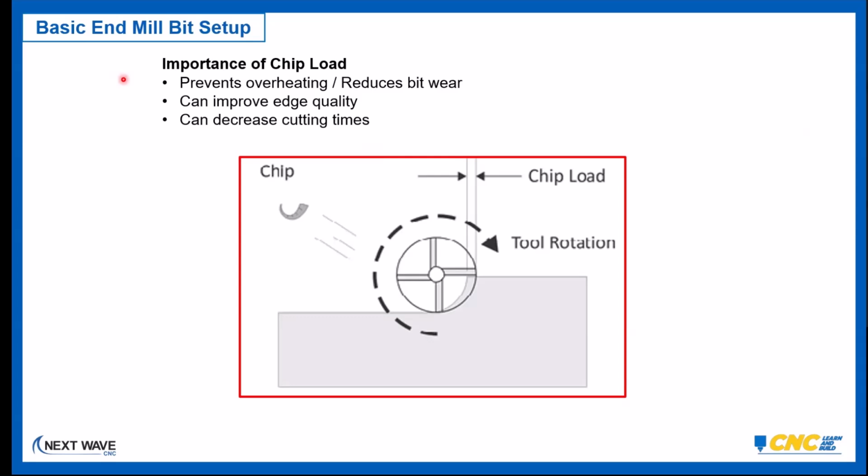So you get the best mileage and the best tool life if you prevent your bit from overheating. And the best way to do that is maintain a good chip load, because by maintaining a chip load, every time that bit bites the wood, it's like going into cool material. So it helps to cool the bit. The heat actually goes into the chips. When you run some tests sometime and you're getting a good chip load, if you can safely grab some of those chips and feel them, they'll actually be hot or warm, because that means the heat is coming off.